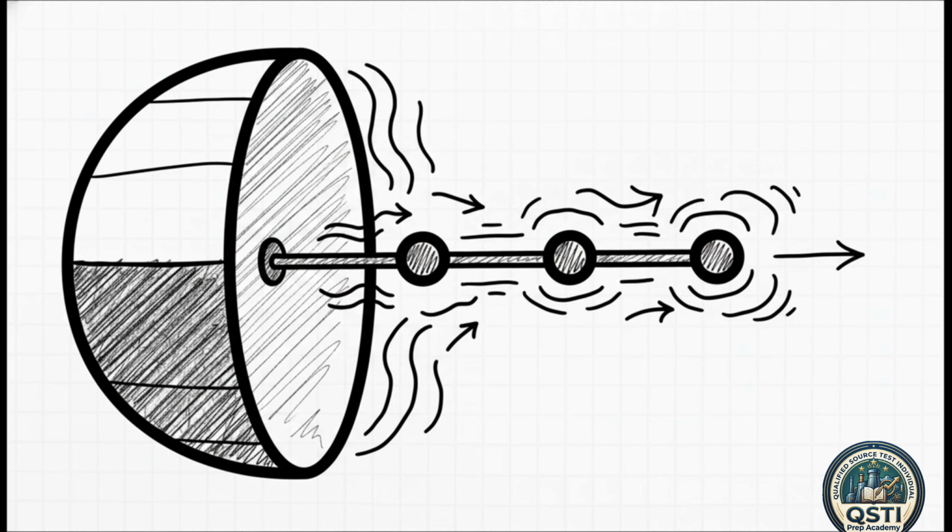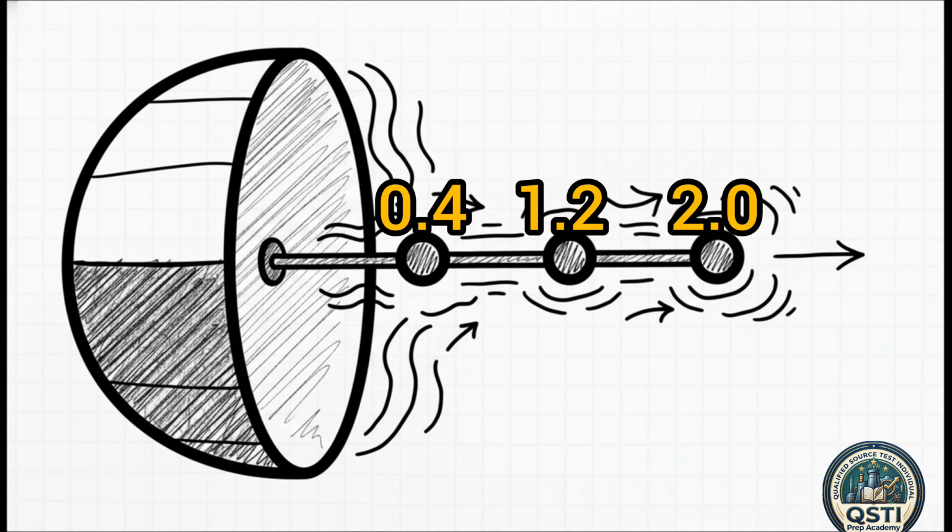And when you're actually testing that flow across the stack, you've got strict traverse point requirements. Let's say your measurement line is a long one, over 2.4 meters, and you aren't expecting the pollutants to be stratified or layered unevenly. The rules give you these alternative traverse points. You measure exactly at 0.4, 1.2, and 2.0 meters away from the stack wall. This means no operator is ever just guessing at the cross-section of the gas flow.